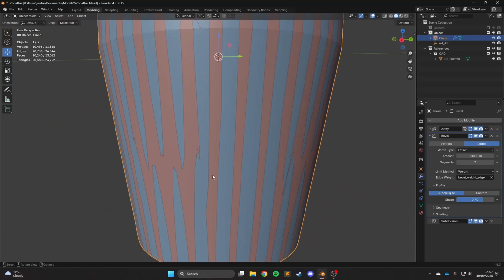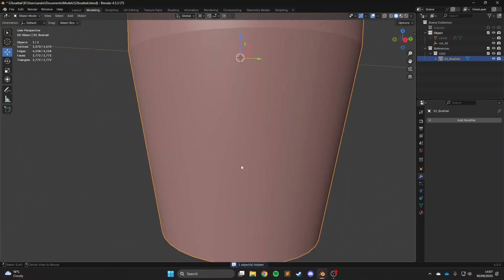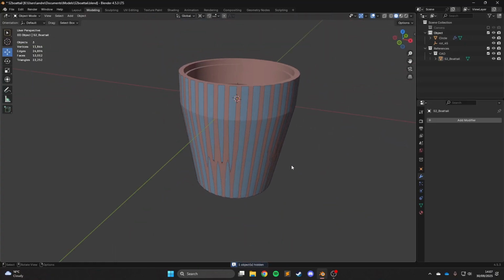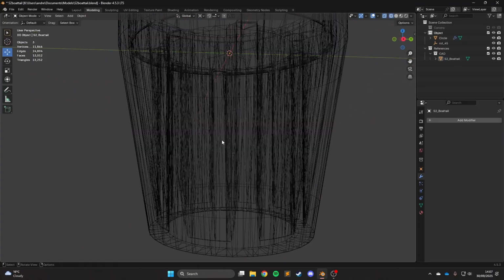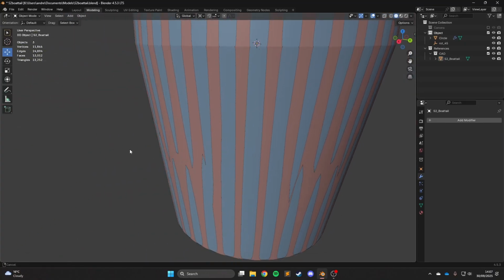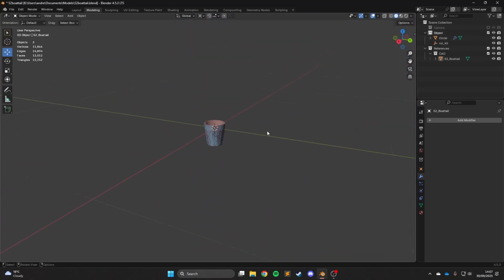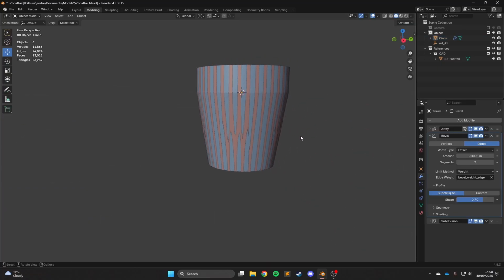Now you can see, because the geometry that was exported from Fusion is a bit weird compared to our Blender model, that's why you start to get the kind of weird Z-fighting here, where they're not really sure which face to display on top. And if you zoom out, it starts to get really bad, because of floating point precision errors, as you zoom out you start to get all of this fighting here. It thinks the two faces are on the exact same position, so it doesn't know which one to display.